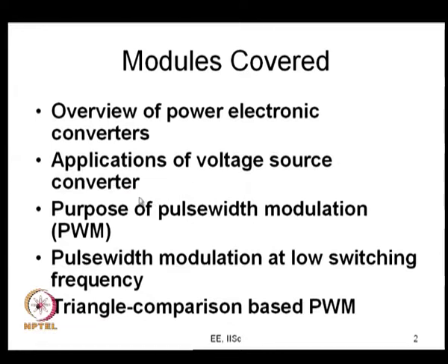of voltage source converters. One application, for example, is motor drive, which again is a focus area here. You can also look at active front end converters or power factor compensated rectification, and they are also used as voltage source converters. They are also used for harmonic compensation and reactive current compensation, etc. So, we had an overview of various power electronic converters, and we also looked at the applications